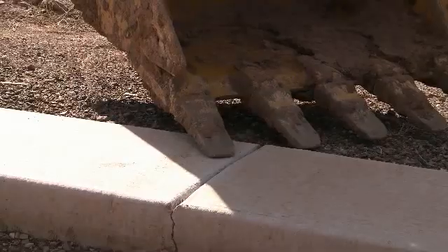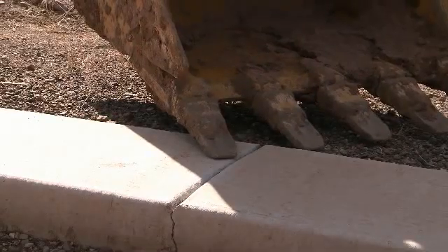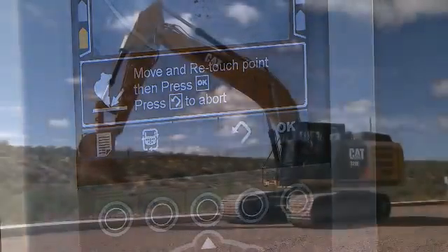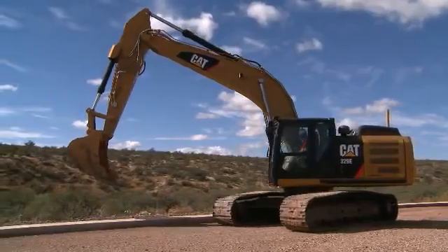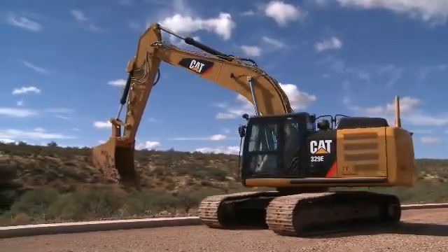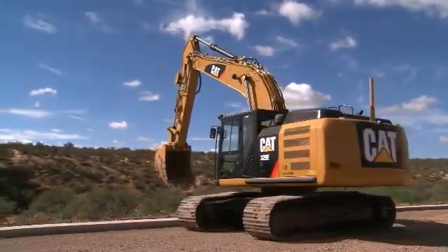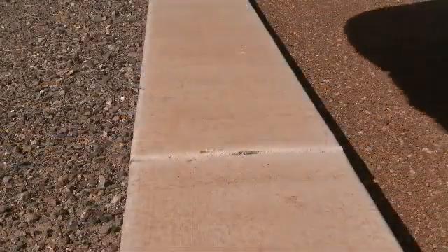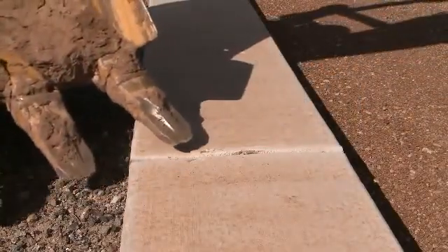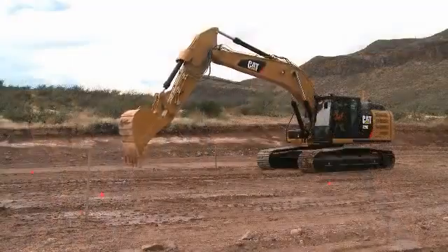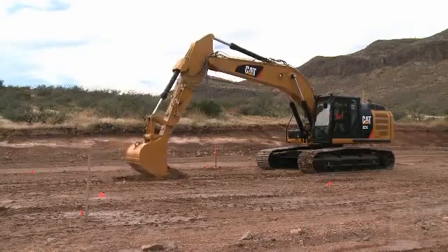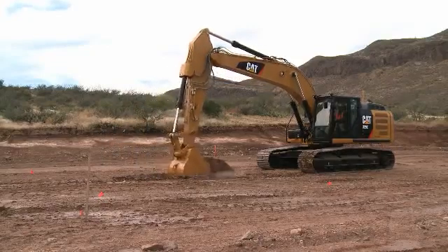Touch any place within reach that can be reached again after the machine is moved. Use the touch point button or the left trigger and left button on the joystick. Move the machine to the new location and touch the same point again. Use the display or joystick combination to accept the new position. Any undercarriage elevation change is calculated, and the reference elevation is automatically updated.